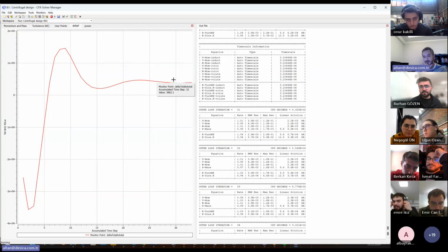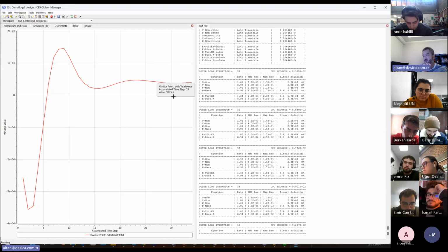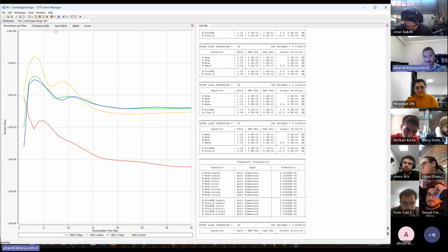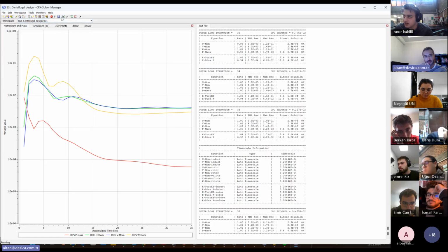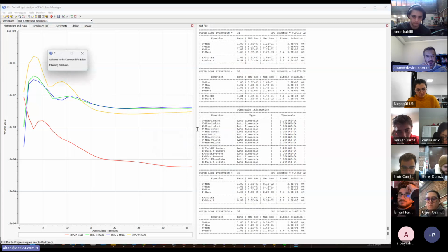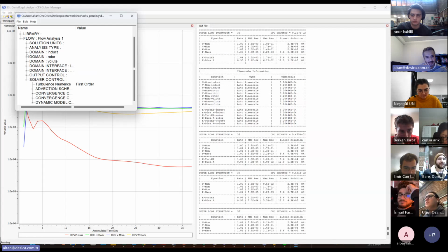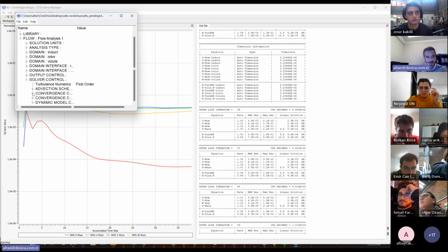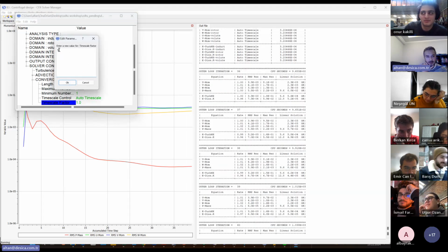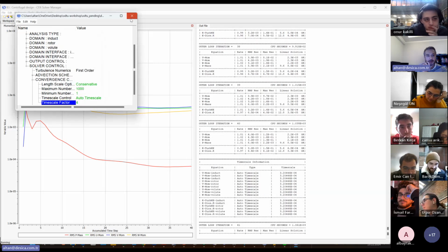according to my monitor point, delta pressure is slightly lower than expected, but not converged yet. We should wait some. I can boost the solution by adjusting the time scale. Although it's a steady state, there's a time scale here in solution. But do not try it at home.